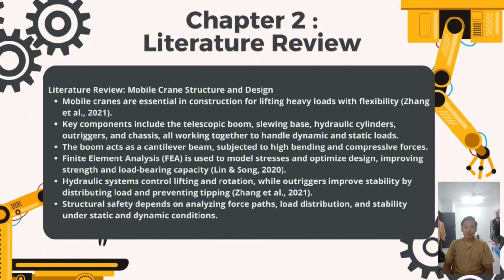The boom, functioning as a cantilever beam, is particularly critical as it withstands significant bending and compressive force during operation. Lin and Song 2020 highlight the use of engineering tools such as finite element analysis to simulate stress distribution and optimize crane design.